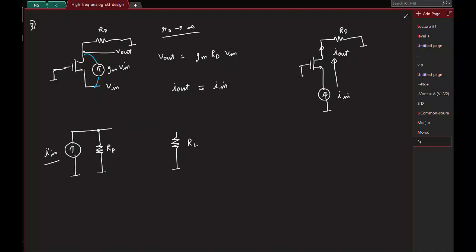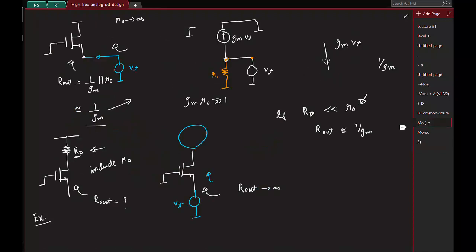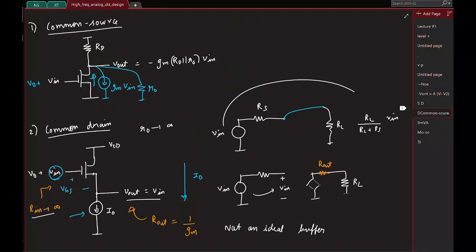And that is why you put a current buffer, which basically provides a zero input resistance, so that the current source completely transfers its current, and then this guy will make a copy of this current and transfer it like this. Okay, so this is basically a current controlled current source. And similarly, this guy, where did it go? The voltage buffer is what kind of a control source?